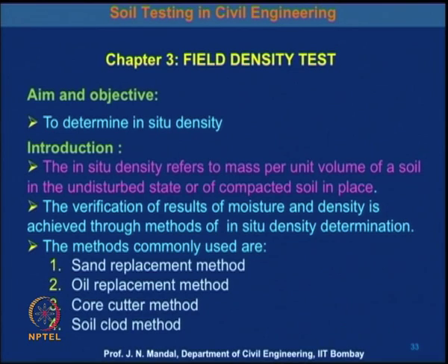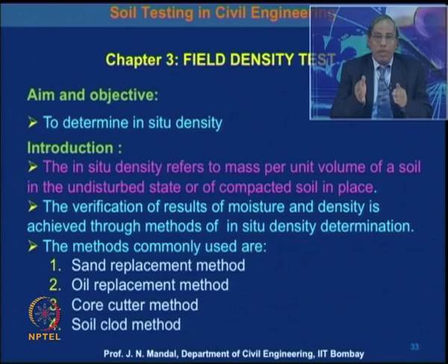It is very important that one should collect the undisturbed soil sample, not the disturbed soil sample. And then the verification of the result of moisture and the density as achieved through the method of in situ density determination.